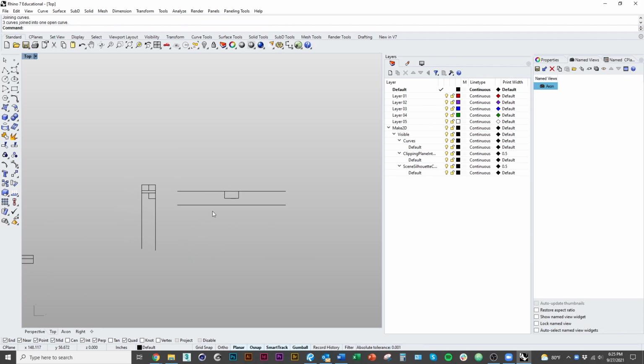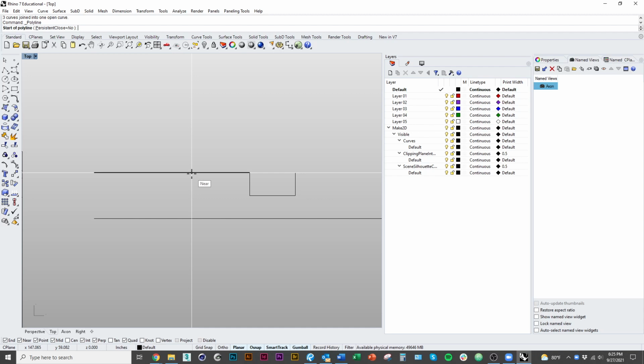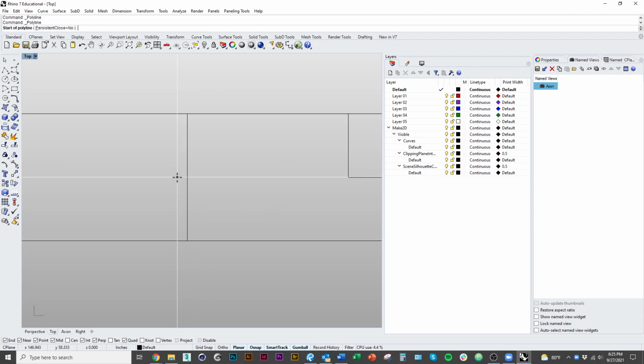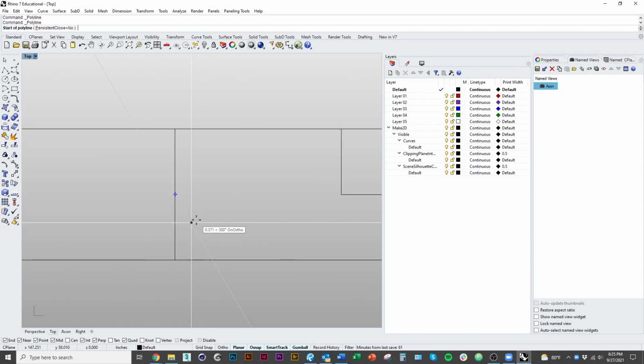Now, typically you have this thing kind of cut off. We don't need to know what's going on way over there. It's just about that single connection. So you can draw one of those little zigzaggy lines. I like to draw a line just wherever I want to cut off the drawing, basically. And then I'll use the command line. So not polyline, but just line. I'll choose the option bisector, I think it is. Nope, I was wrong. Both sides, sorry.